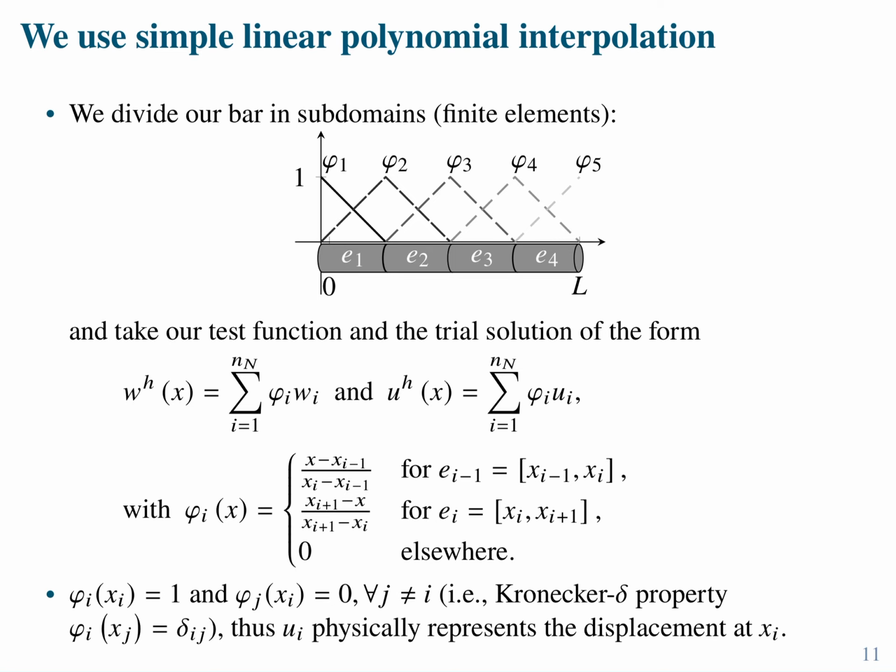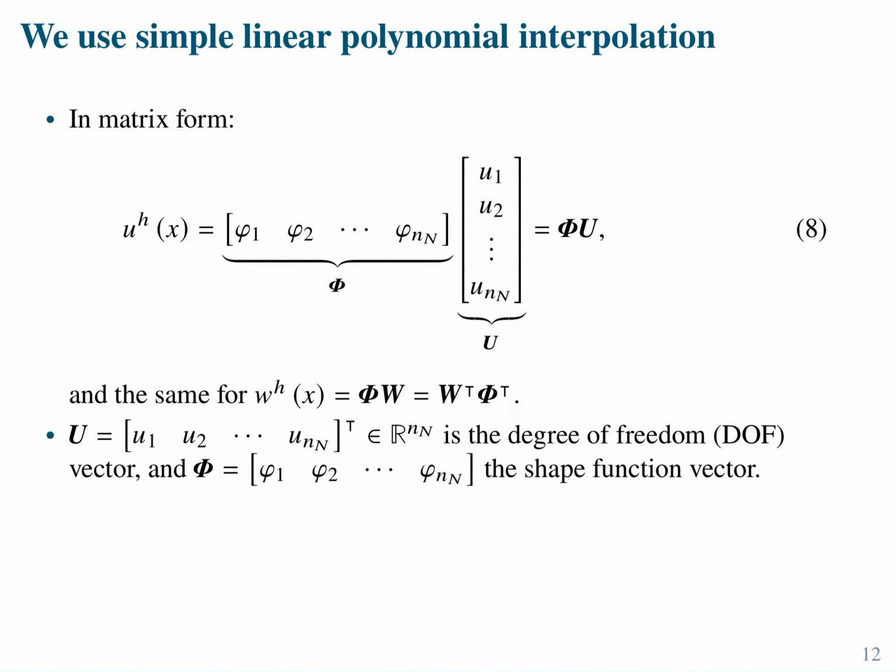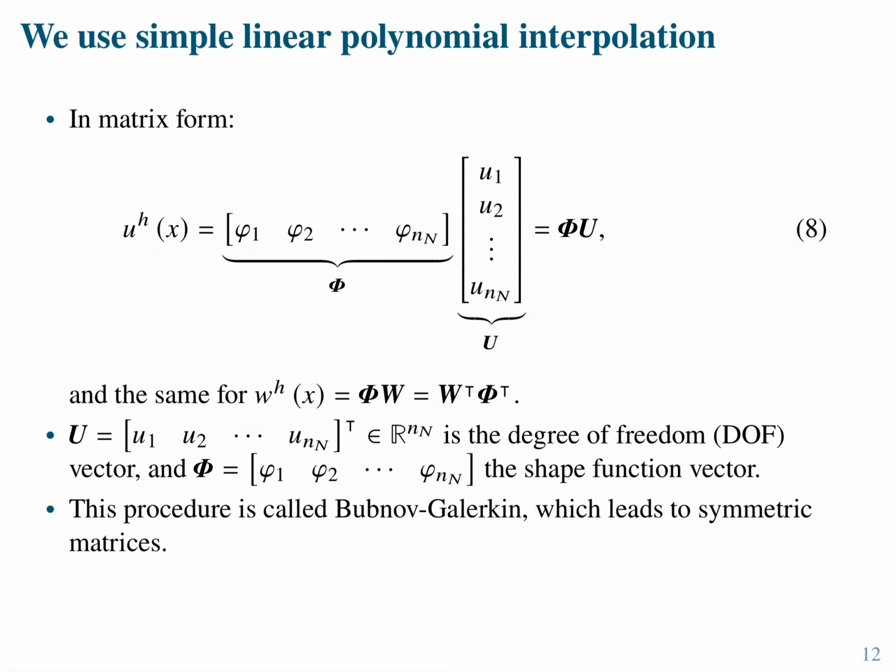Again, finite element is a wild field. You can do all sorts of crazy things. So you can pick, for instance, trial solutions from one space, and you can pick the test functions from a different space. That is something completely different. It's not called Bubnov-Galerkin. It's called Petrov-Galerkin. And for instance, Petrov-Galerkin was the solution to using finite elements for computational fluid dynamics. Before the introduction of the formulation for Petrov-Galerkin, it was not possible because you had tons of oscillations for advection-diffusion problems.